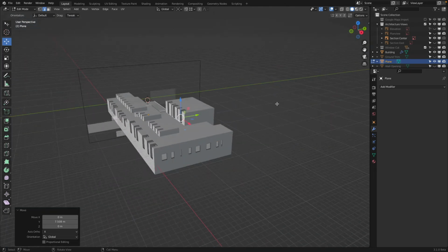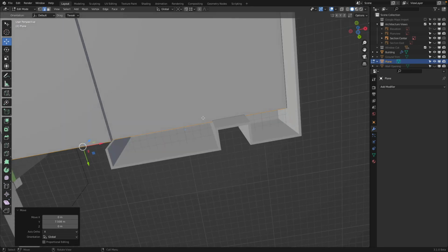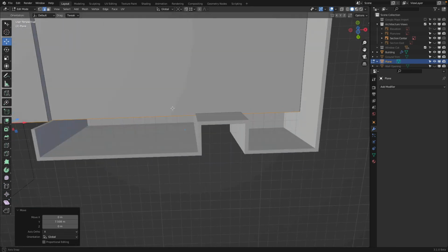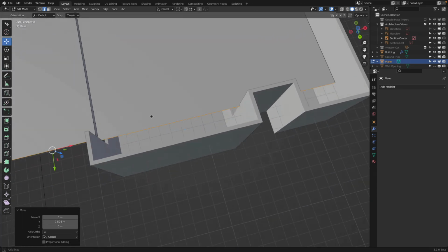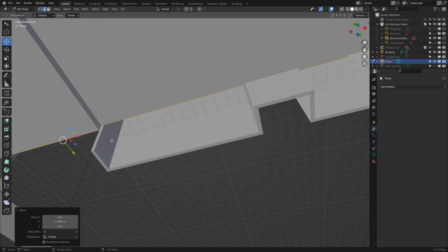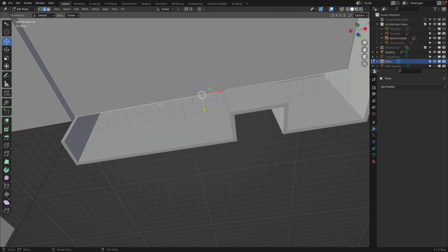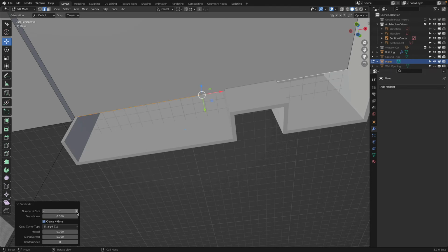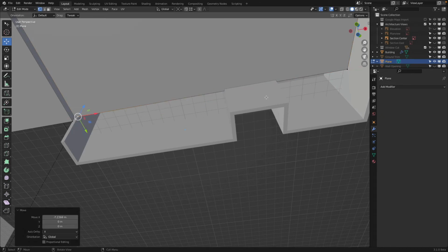Now, how do we do the space inside? Maybe this view will be useful. I need to have geometry that goes in there. That's very easy to do. I can select this edge, then right click and say subdivide. And here I say, please, 2 times. Click. There's 1 point. Move this over along X, hold control, snap to there.